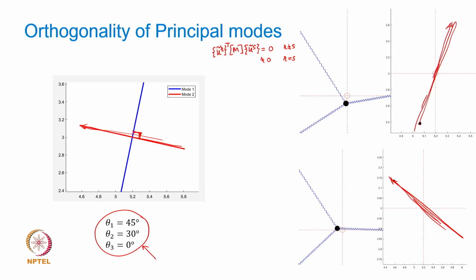Now if an additional degree of freedom, let us say z, appears, that is, if this mass is moving in a 3-dimensional space, then you will have another line about which it is going to vibrate, and the three modes will be orthogonal to each other. Then in an n-dimensional space you can treat that to be n mutually perpendicular vectors.